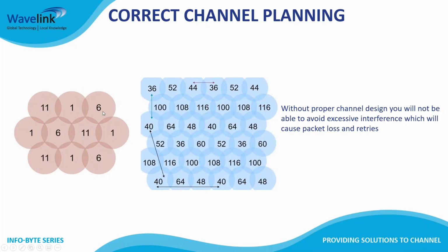A great example over here again of 802.11 and 2.4 gigahertz and its complete lack of capability in terms of its channel reuse as well. And of course, if you had all of these deployed, all of those radios on the same channel will be able to hear each other and will be causing some co-channel interference with each other as well, because of just how far the signal can spread at its lowest data rates.